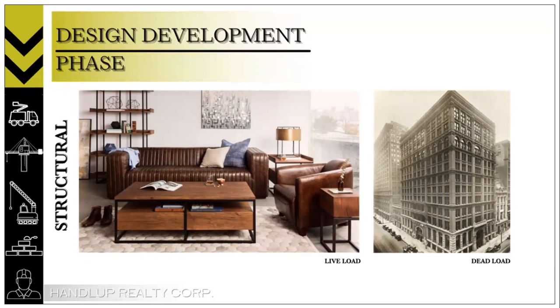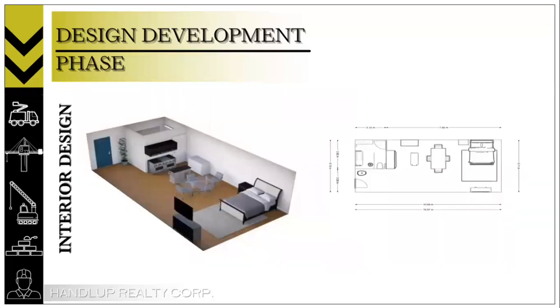Loads prescribed by codes are empirical and conservative, based on experience and accepted practice, while dead loads, also known as permanent or static loads, are those that remain relatively constant over time and comprise, for example, the weight of the building's structural elements, such as beams, walls, roof, and structural flooring components. Other than that, since the company will only use bare finish for the other rooms, we have prepared a standard design room which includes the essentials of the room as you can see in the presentation.